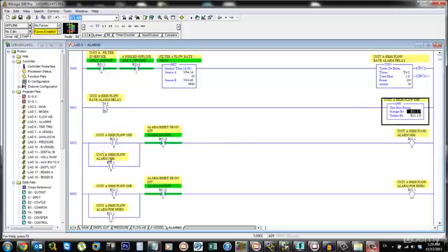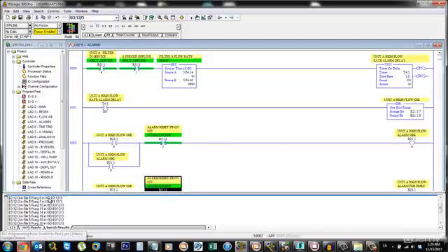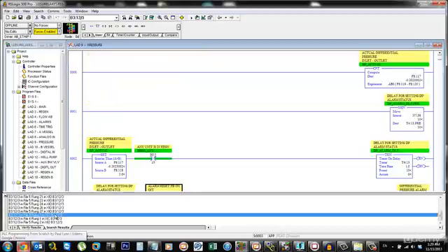So if I have an alarm reset push button on OIT, such as this one here, and we'll get into what all of this means later on in the course, but we have an address B3123, I can very quickly just tell it to find all, which is the same as typing it up in this box and using this command here. And it will tell me very quickly, right down here in this bottom pane that appears, exactly where I can find that memory location throughout the program.